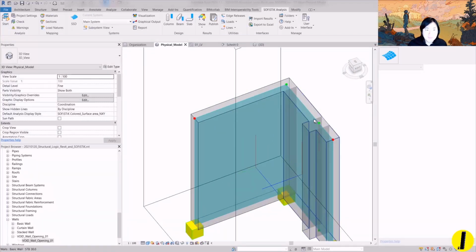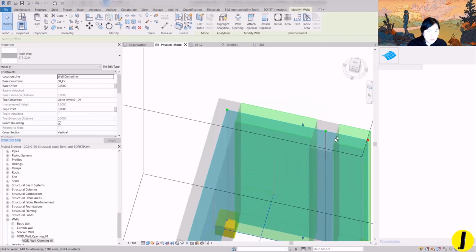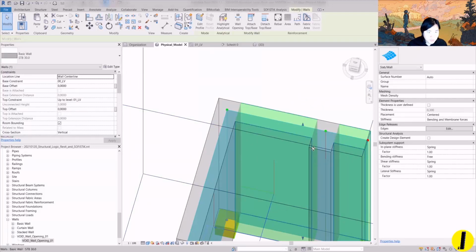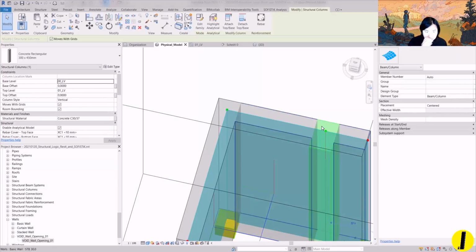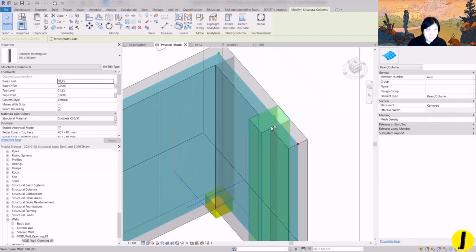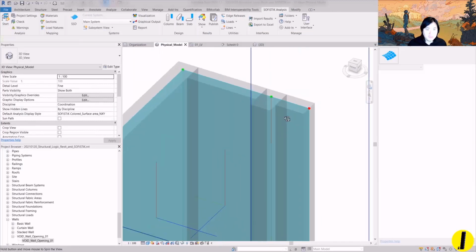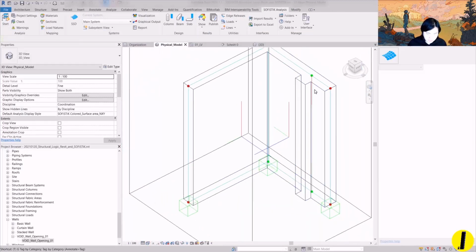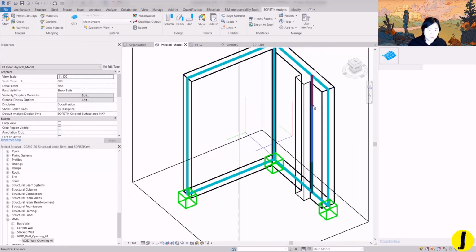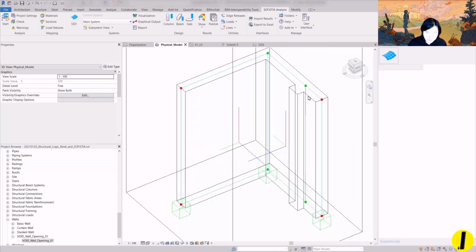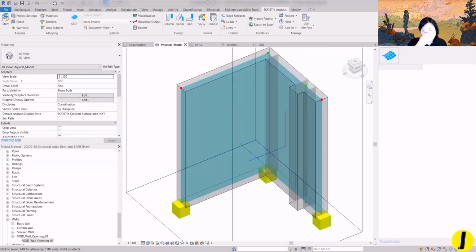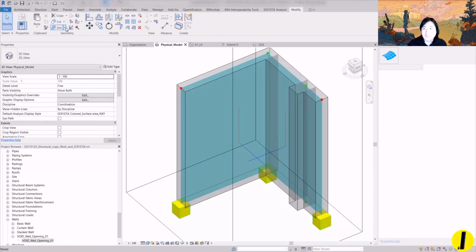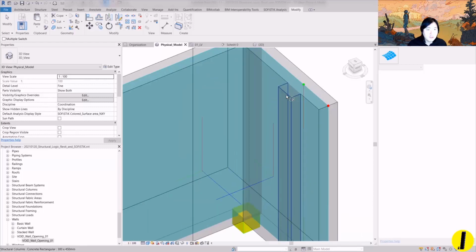example, but this time the wall is split at the joint with the column, and the column geometry is actually there, but the analytical model is the same as the previous one. As you can see, the analytical surface and framing is the same. It's just physically, what I did was on the Modify tab, you have this Join, and we can switch join order. When you switch the order, as you can see, the column is embedded in the wall structure.